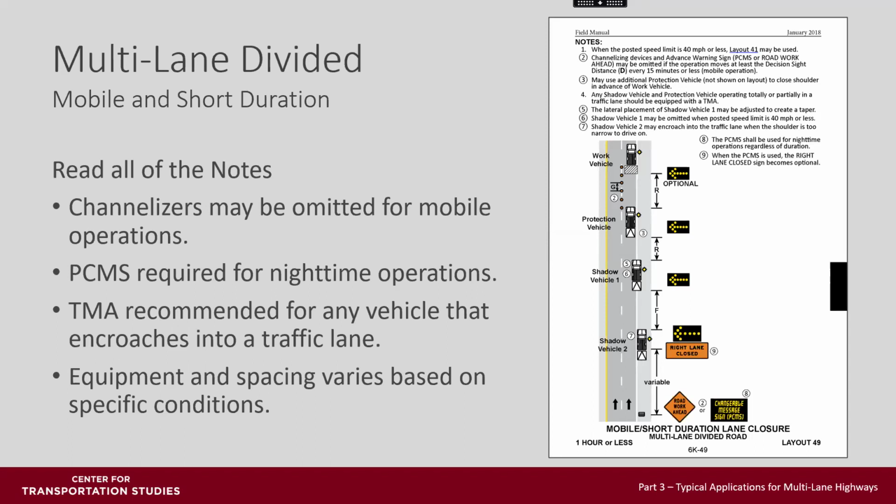A special note with these and other layouts in the field manual is the difference between required or shall be used, which is a minimum standard, like the changeable message sign here, and the truck mounted attenuator is recommended. It should be used, but is not required to be used.